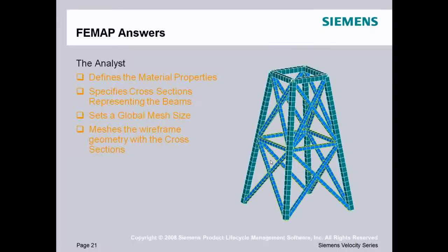You can very quickly edit the material properties and/or the cross section properties and change the thicknesses of the tubes. And you can also very easily add or remove stiffening tubes to kind of optimize your design. So it's kind of the point of idealizing the structure as shown. But today we're going to look at setting up the model for linear buckling versus non-linear buckling.